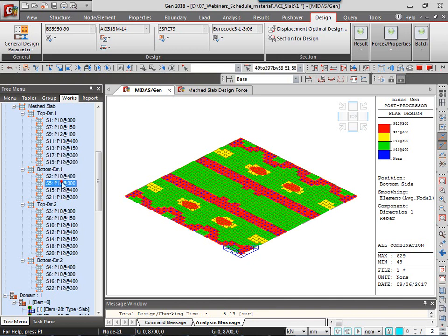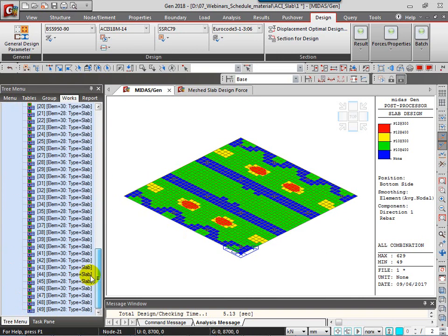After I click on update rebar, all the reinforcements are randomly assigned to the elements. However, when it comes to practice, we are supposed to provide uniform reinforcements. So for that reason, we'll be assigning the reinforcements onto the slabs by using the subdomains that we have generated.